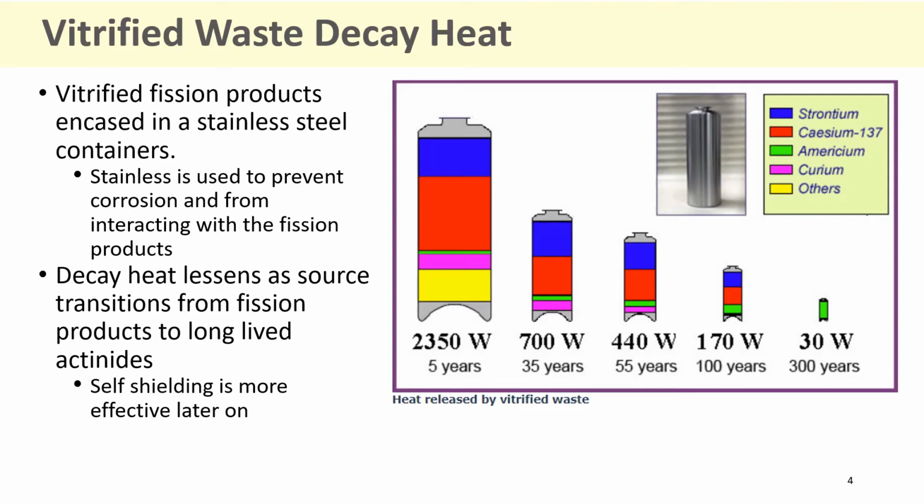This is because the nuclear glasses are formulated to be poured at 1100 degrees Celsius, while the melting temperature of industrial glasses is significantly higher. This also minimizes the volatility of radioactive components such as Tc-99, cesium-137, and iodine-129. Glass transition temperatures occur in similar ranges, although slightly lower for nuclear waste glass compared to normal glass. The thermal expansion coefficient of the nuclear waste glasses is similar to that of window glass and significantly higher than that of Pyrex that you'd use in your kitchen. Pyrex is formulated specifically to resist thermal shocks, so you can go from hot to cold a lot easier without it shattering on you. Thermal conductivity is similar for all three types of glass.